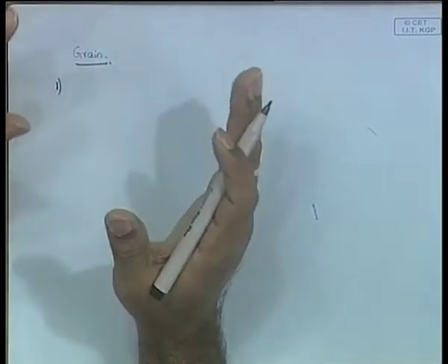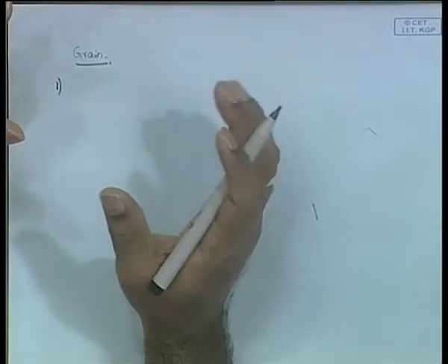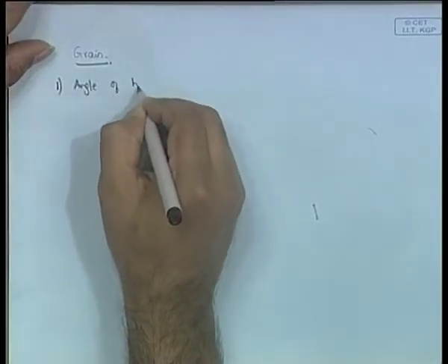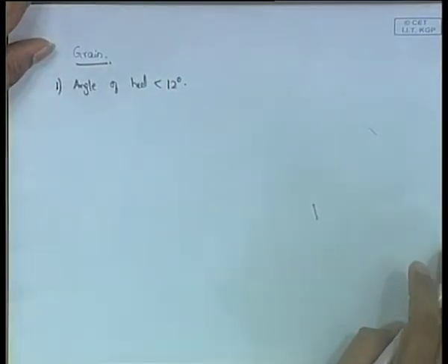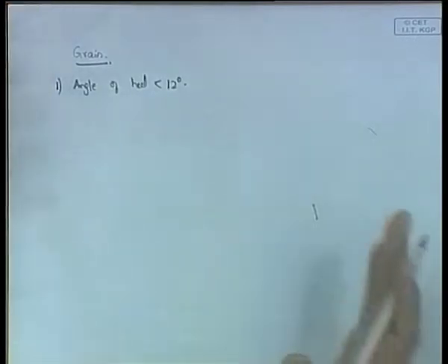Now, when grains are put into the container, and because of the grain shift, there is a heel of the ship. The rule says that the angle of heel should definitely be less than 12 degrees. Because of the shift in the grain, there is a G0 G1, which means a shift in the center of gravity, as a result of which there is a heel.